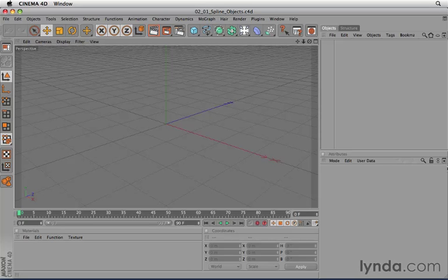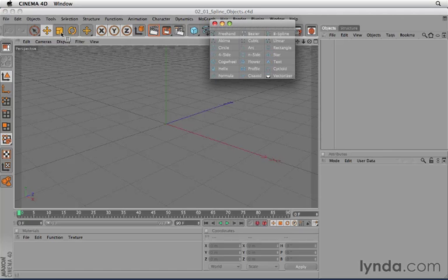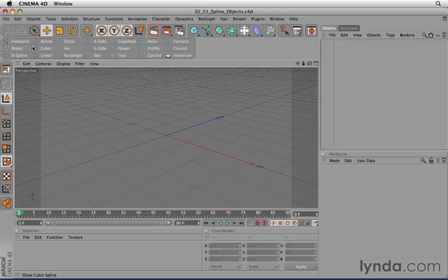Then we can move through the rest of this chapter using splines to create NURBS objects. So to create a spline in Cinema 4D, go up to the spline pop-up menu, and let's go ahead and just rip that off and add it to the top of our scene, just so we can reference it as we move throughout the rest of this video. And since I mentioned path splines in Photoshop and Illustrator, let's get started creating a Bezier spline path.